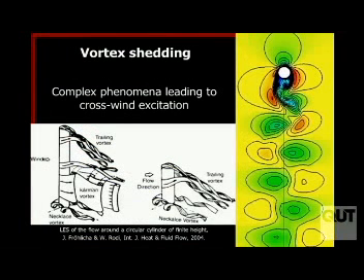And why do we get this lateral loading? Well, again, it's a fundamental phenomenon in fluid mechanics that if I have a flow and a linear two-dimensional structure, then as the flow takes place around that, I will generate separation from that, and under certain circumstances I can get now a street of vortices.